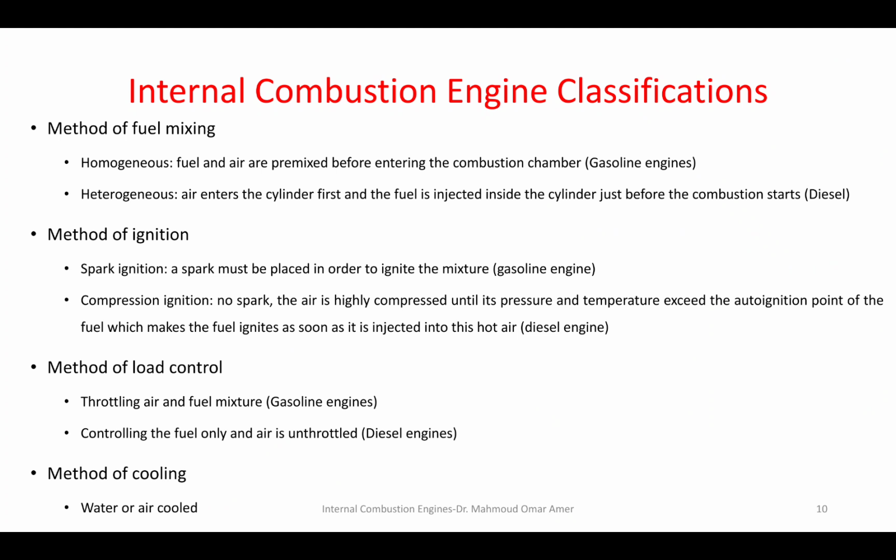Homogeneous means that both air and fuel mix very well before combustion, which is the case in the gasoline engine. In the gasoline engine, the fuel starts mixing with the air at the intake, before the intake valve, in the intake manifold. And it mixes during the intake stroke and during the compression stroke. So the mixing is very well, and it's called the homogeneous mixture. But in diesel, we inject the fuel at the end of the compression stroke. So it has a very, very short time to mix with air. So it's called the heterogeneous mixing, and the mixture of air and fuel isn't that good.